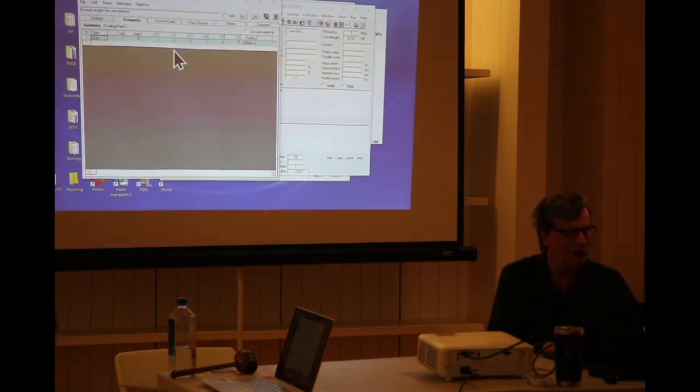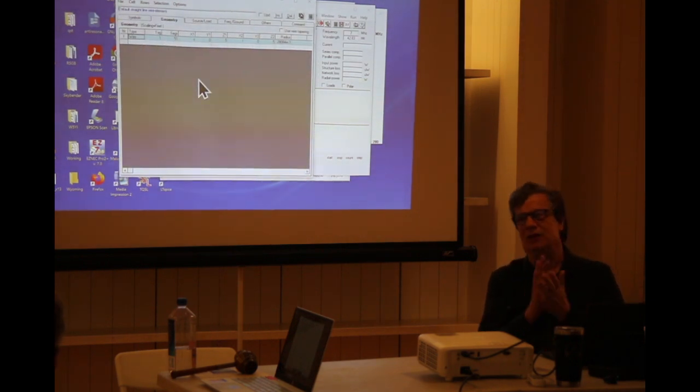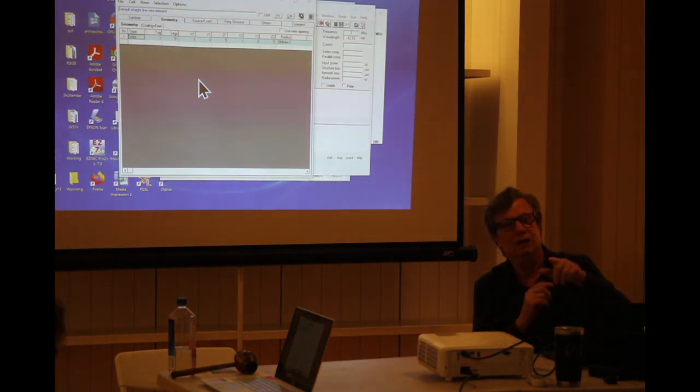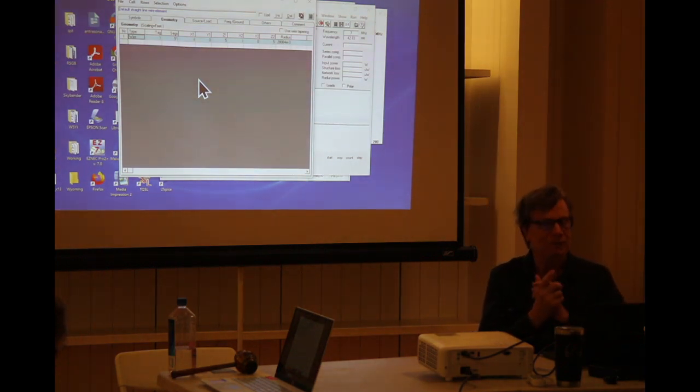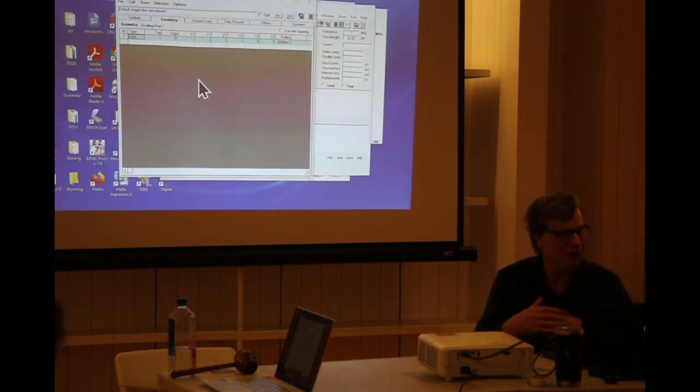So what we have here is the table, and if you're using EZNEC, everything's done this way anyway. EZNEC does not have the graphical input, although it will show you after it's already built. We have a wire with 51 segments, and we always want to choose an odd number of segments so you can put a generator exactly in the middle. Otherwise there's no way of putting it exactly in the middle. So 51 is a good round number.